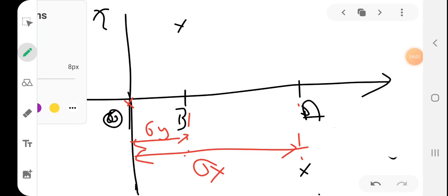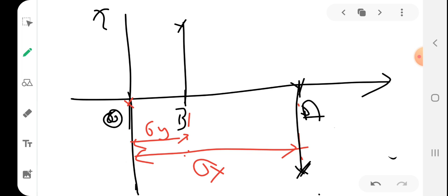So students, you do one thing. In case of sigma x, you draw negative tau, and in case of sigma y, you draw positive. Now you have to join this. Okay, you have to join this. Suppose this point C will definitely bisect AB.